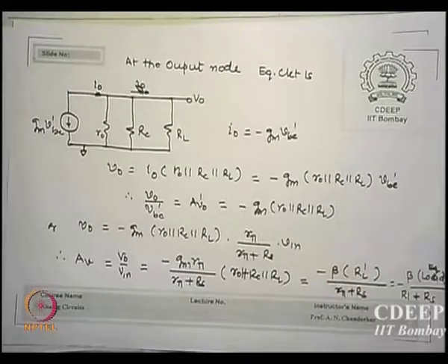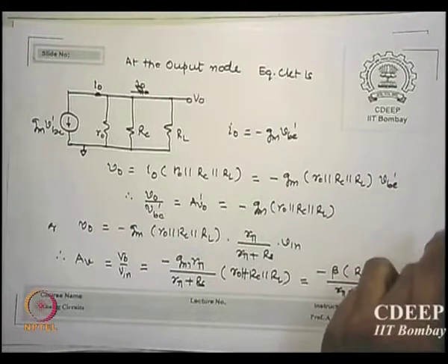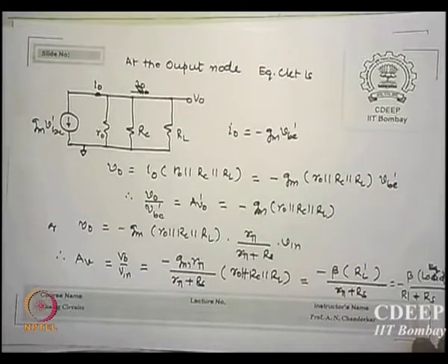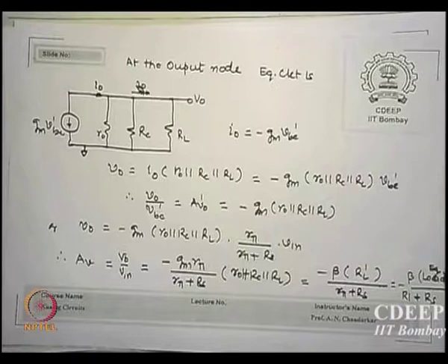Here beta is 100 plus. Please remember, even if the load is equal to Ri plus Rs, with beta being 100, the gain you are getting is 100 if I use bypassed. If I put an unbypassed emitter resistor, it is just RC parallel RL divided by RE, that is it, but it is independent of beta, is that okay?